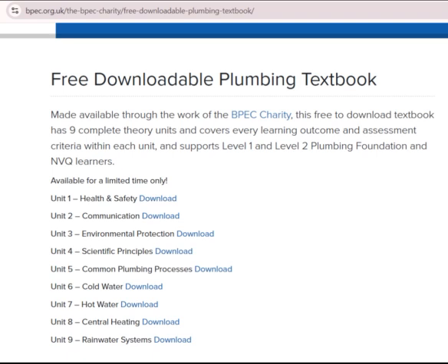1. Consult with the customer and decide on the position of the radiator. 2. Mark the center of the radiator and the position of the hangers on the radiator itself. 3. Mark the center of where the radiator is to be hung on the wall, and place the radiator center against that mark. 4. Mark the position of both brackets on the wall. Using a spirit level, draw 2 vertical lines where the radiator brackets are going to be positioned.